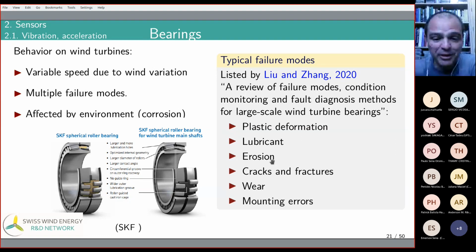If temperature increases, perhaps you have plastic deformation. Temperature always increases because it's something rotating, right? The temperature is high on a shaft that is rotating, of course, and you have oil there to reduce friction. And perhaps you start to wear out and then you have particles in the oil and then you start erosion. So these things all happen at the same time.